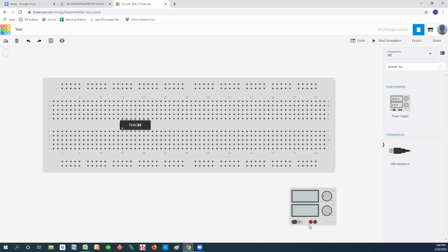All right. So another general thing we do with prototype boards is, instead of going from the power supply directly to each component, we could have 30, 40 components in here. We don't want to draw a wire always from the power source to it. And if you recall, these pins are all connected, and you see there's a plus sign next to it. And these pins are connected, and there's a minus.